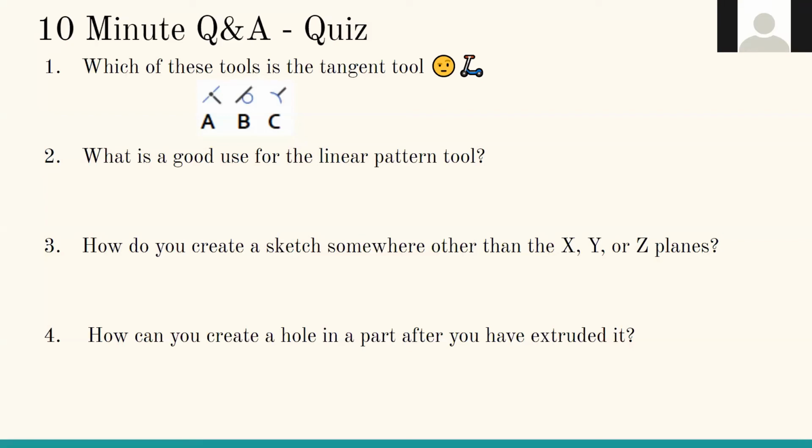Waiting for people to type stuff up. Does anyone have a good use for the linear pattern tool? No? Okay. Well, the linear pattern tool is good for replicating within parameters for even spacing. Yep, that's a pretty good way of phrasing it. It's pretty good for when you want this one section of your sketch to be repeated multiple times across a larger space, and it can be pretty useful.